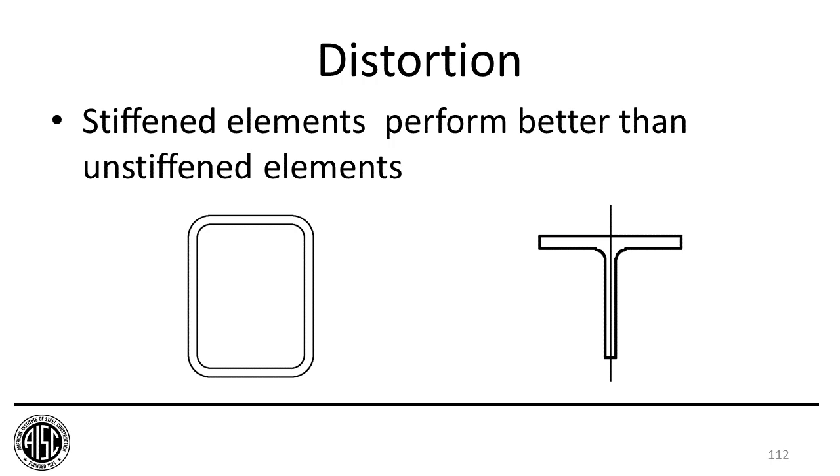One reason that could be true potentially is that the residual stresses in induction bent members are less than in the other members. So it is a topic that I really don't know the answer to, but I do know that they provide bracing. If it is a long, slender member that's going to vibrate on the truck, they will provide bracing for the shipping of that member to prevent any distortion or loss of radius during the shipping.